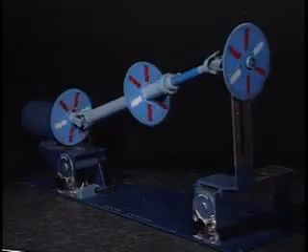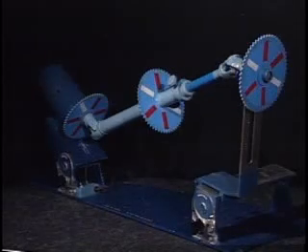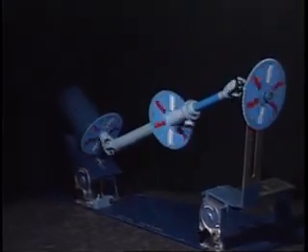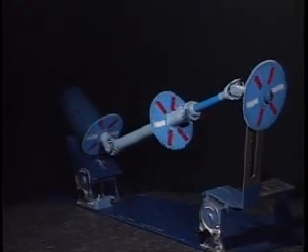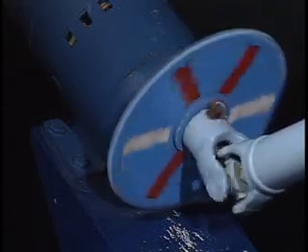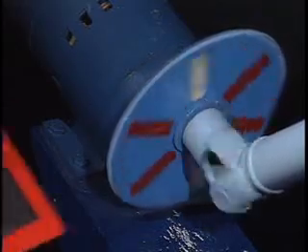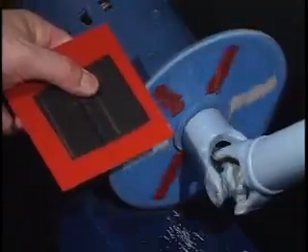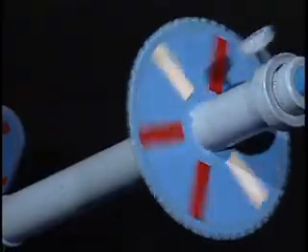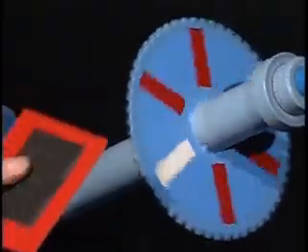We can demonstrate this by changing the working angle of the first U-joint. Now, even though the driveline is in phase, we have a vibration condition. With a large amount of angle difference, the first shaft will rotate at a constant rate. And the second shaft will, as expected, rotate at a varied speed.